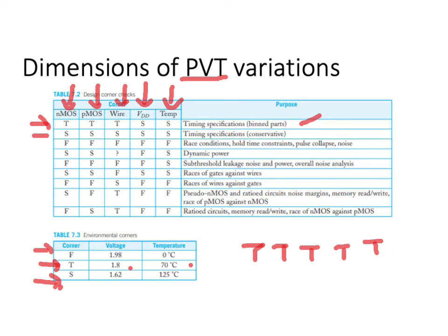And if you are investigating race mode failures, that is failures of the flip-flop to capture the correct values in one cycle, because the values arrive too quickly and do not respect the hold time of the flip-flops, you would simulate at the fastest corner.